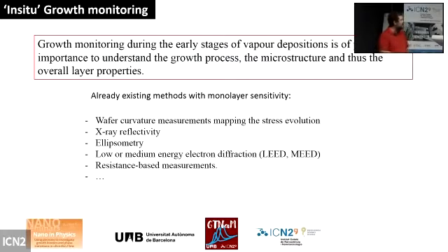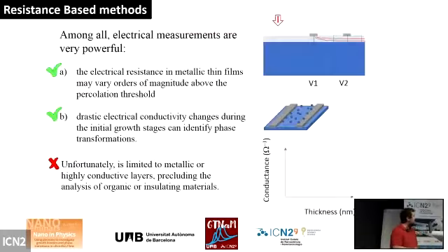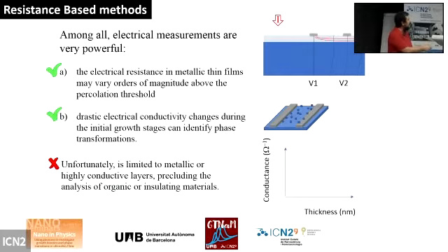This is something that everybody can do in their lab. If they have an evaporator, they can prepare just a substrate that should be an insulating substrate, where I can lithograph a couple of metallic electrodes on top of a highly insulating substrate. The difference in electrical conductance in that case used to be around 10 to the 5 orders of magnitude between the metal and the oxide, the electrically insulating material.